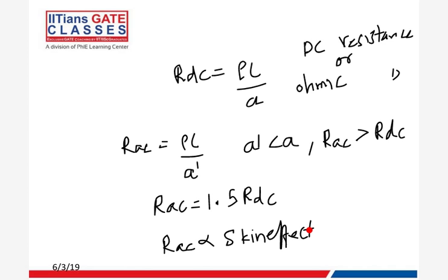So basically what we are trying to say here is that even if we are using a big cross-sectional area conductor, due to the inherent nature of AC power flow, we don't get to use that whole area. So it is effectively the waste of an investment. That is why we tend to go for bundle conductor, because as the area reduces, the skin effect also tends to reduce. And so instead of using a single conductor of area A, we tend to use n conductors of area A by n, right?